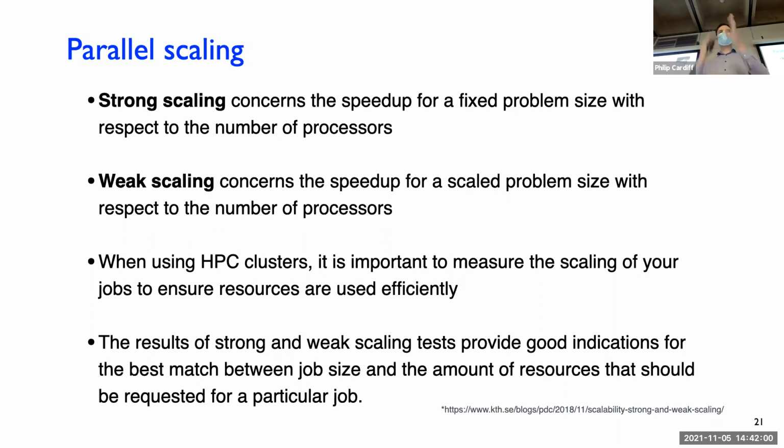A strong scaling study is just where you take one problem and keep splitting it into more and more mini problems that are solved by more and more processors. There's something called weak scaling, where it's the same amount of work per processor and you just start using more and more processors. So if I run a 1 million cell problem, like an OpenFOAM model, on 1 core, then I run a 2 million cell problem on 2 cores, a 4 million cell problem on 4 cores.